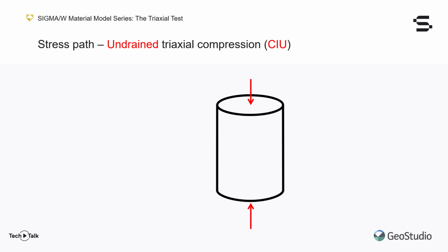undrained triaxial test. For a non-drained triaxial compression test, or CIU, the drainage valve is kept closed, preventing the accumulation of volumetric strains. As the sample wishes to expand or contract during shearing, excess pore water pressure will generate.